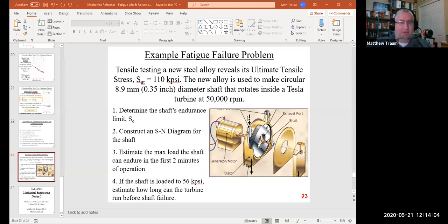The research that I do now, the experimental research, is Tesla turbine research. Tesla turbines are bladeless turbines that can withstand two-phase flow. So you can put basically wet steam into them. And if you took and survived thermal, if you put wet steam into a conventional turbine, it's over, right? The turbine gets destroyed. But Tesla turbines don't care. You can run wet steam through them and they don't mind. So they're particularly interesting for scavenging operations.